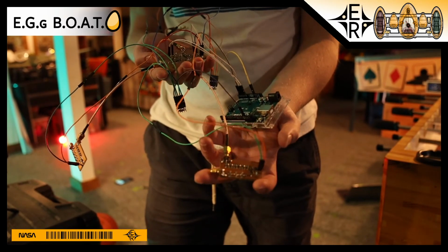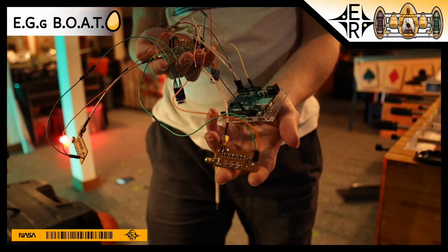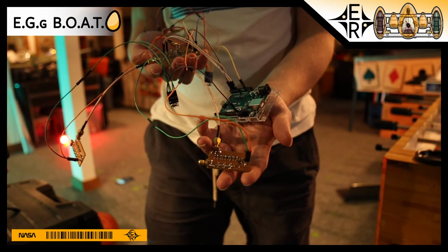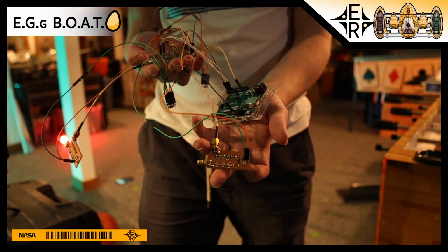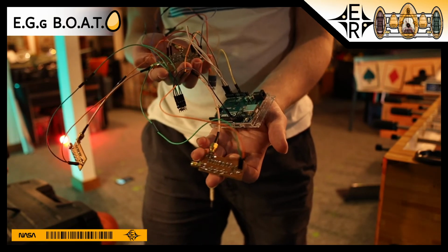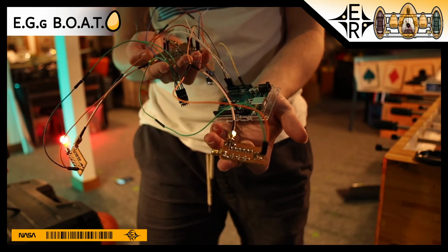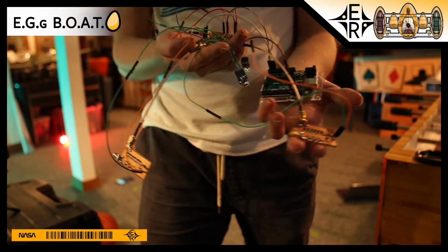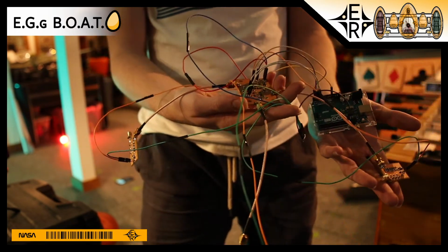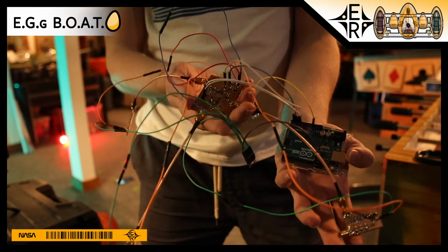What it does is it takes in the antenna right here. It will filter through a bandpass filter for only the 121.65 megahertz signal. It'll then amplify it with a standard RF amplifier and filter the noise out of that amplified signal, leading to an overall linear gain of about 7 to 8 with testing. So we have 3 boards, 1 for each antenna. Those all go to the center board, which does the phase comparison.